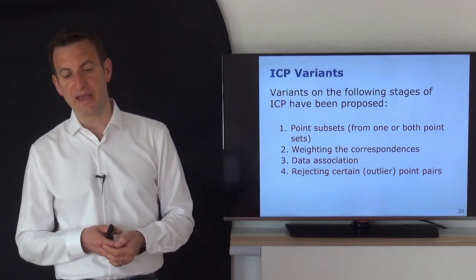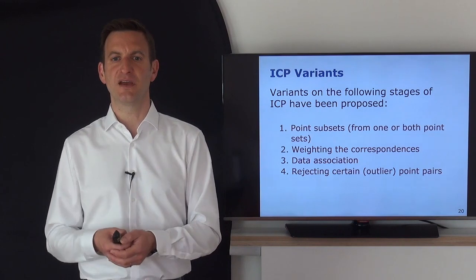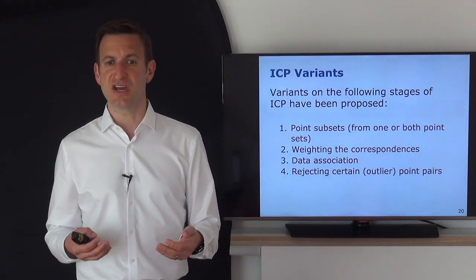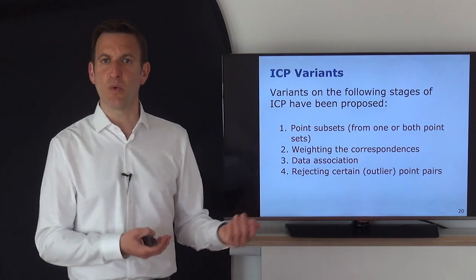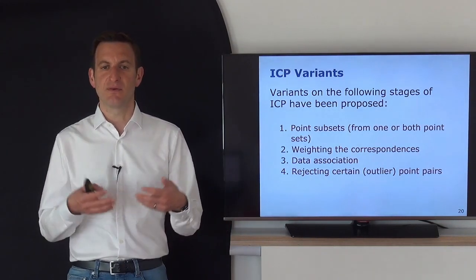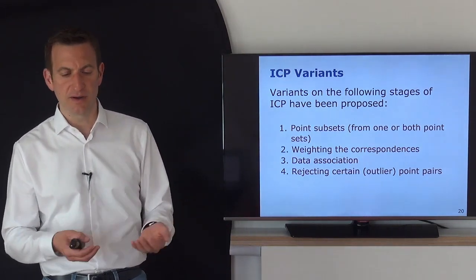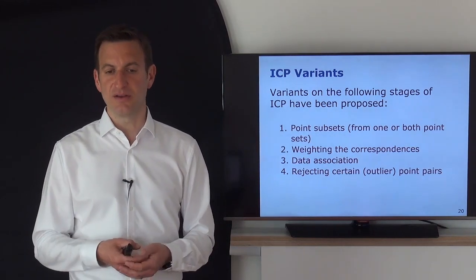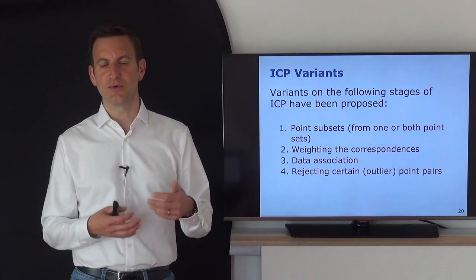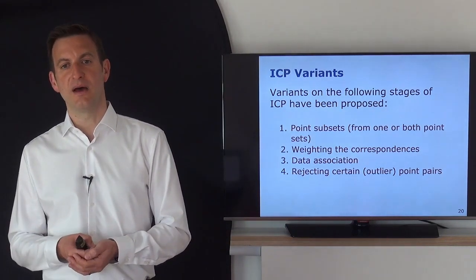And I may also want to take outlier rejection techniques into account. So in practice, we will make data association mistakes. Even if we have a very sophisticated data association technique, there will be errors in our data association. This can be due to the environment actually changing. So consider you're taking a laser range scan and persons are walking by and walking through your scans. If you take the 2 scans at 2 different points in time, the person has moved and therefore corresponds to the same physical object, but the physical object has moved. Then you will introduce errors in your scan if you take them all into account, assuming that the points would be steady. But there can also be other reasons. Occlusions can also be an issue. So we are likely to make data association mistakes, and the question is, how do we reject those outliers or gross errors that we may find in our scans?